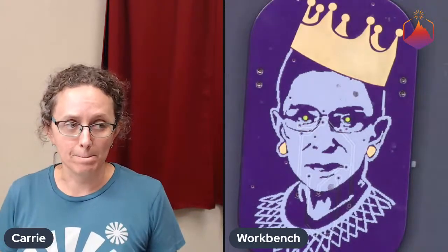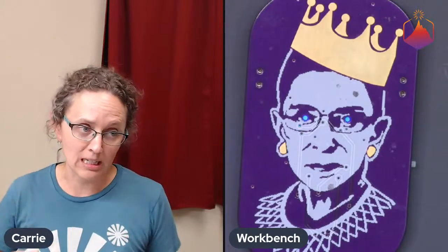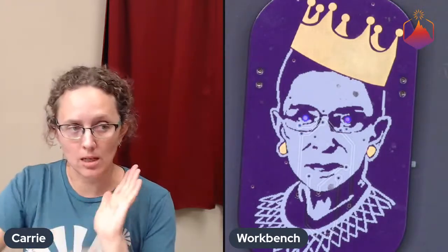And then her face, the white is all silkscreen. So it's all this epoxy ink that's layered on top of the circuit board. The gold, what you're seeing is bare copper, and it's been gold plated over top of that, which is a very common finish for circuit boards.